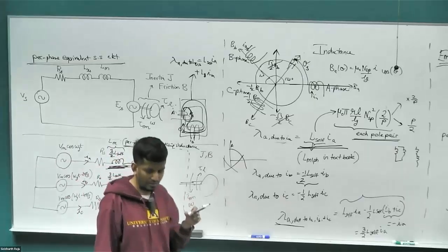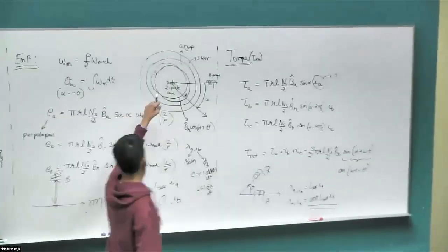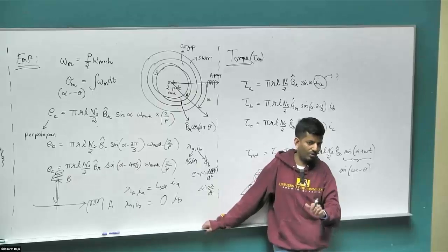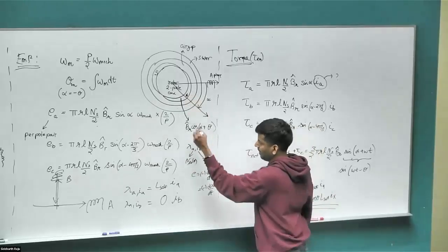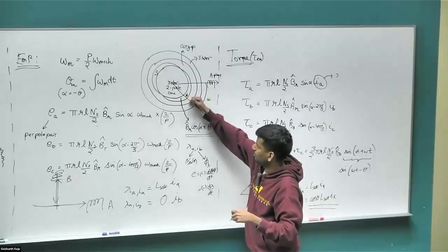Now there is going to be another magnetic field in the air gap due to the rotor magnets. So think of it as two separate magnetic fields. One magnetic field is due to the stator windings, and another is created by the rotor magnet. And again, we looked at last class how we shape it such that in some portions it's a very small air gap.